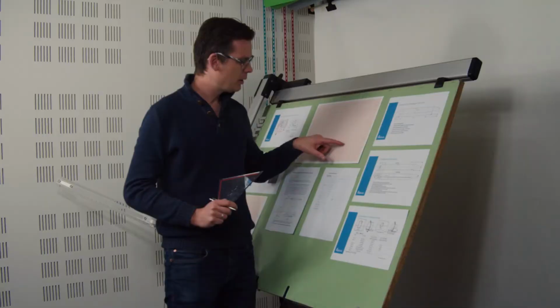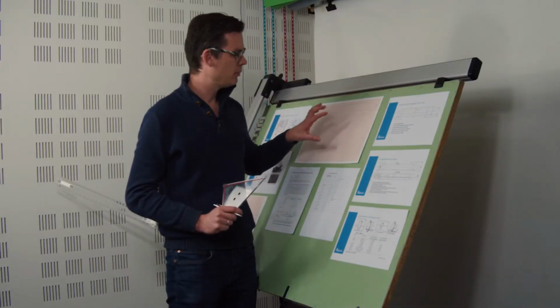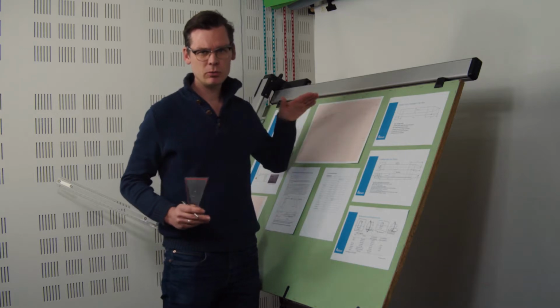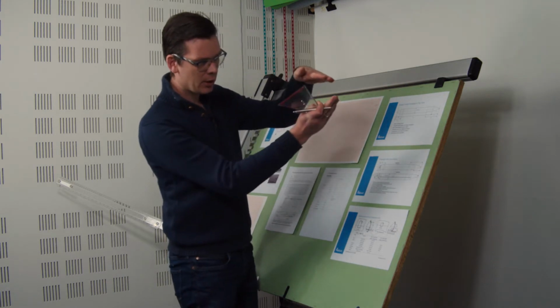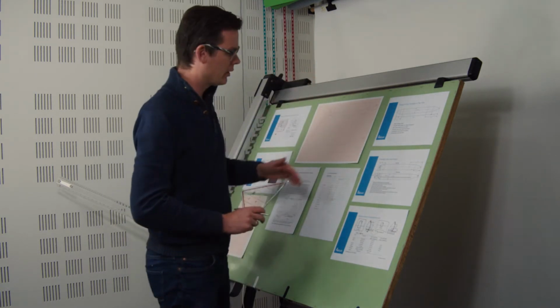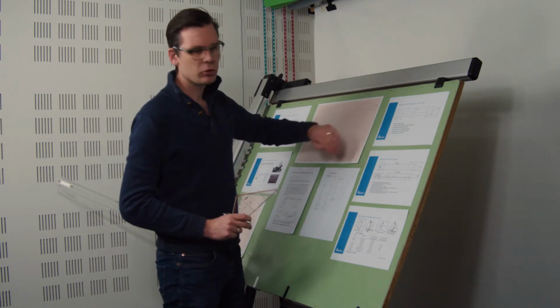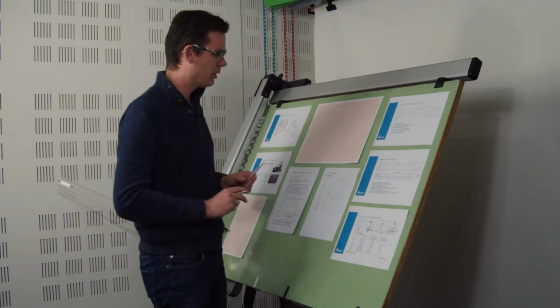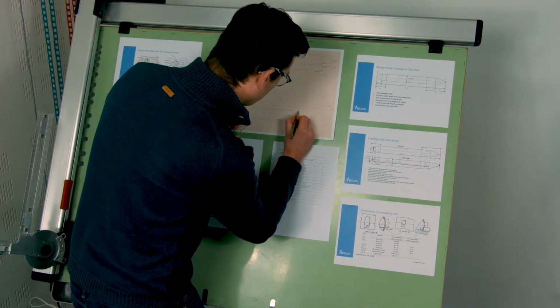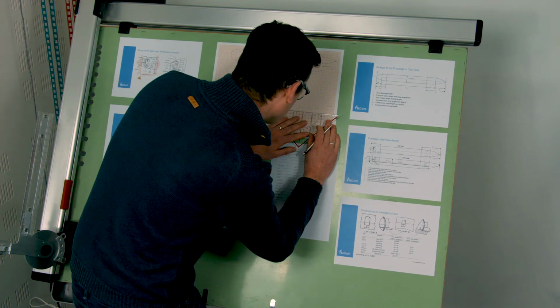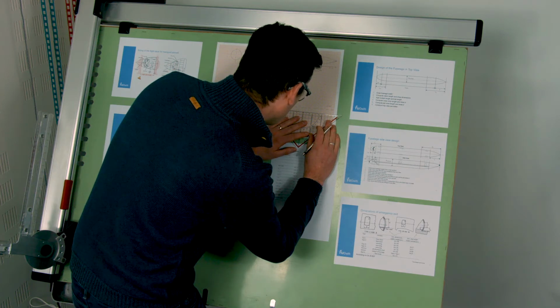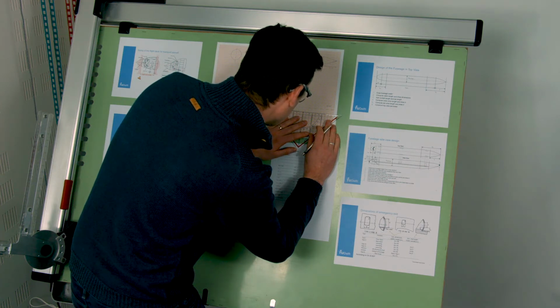Now, just to be clear, you don't necessarily in both the top view and the side view need to converge to a point. Many fuselages actually converge in the top view to a point, but in the side view actually there is a vertical line there. So that's still totally okay. So let me try to make again, I'm using a little bit of a help line here just to guide me, because drawing these shapes is sometimes a little bit harder than you think.